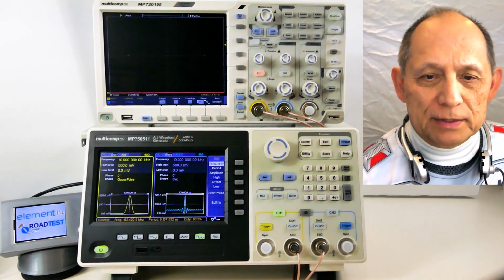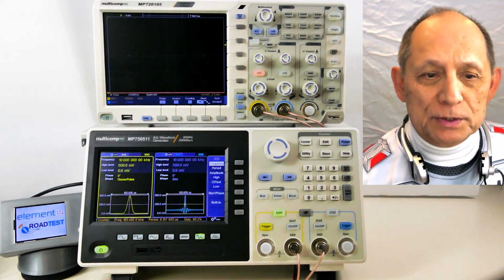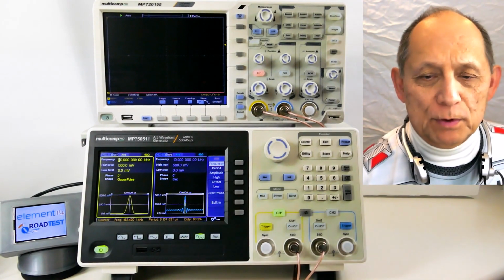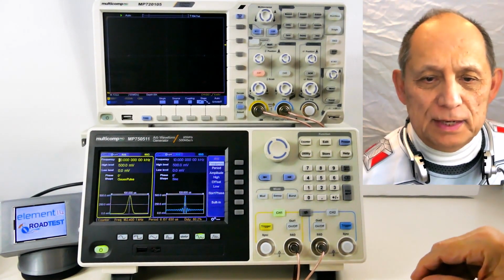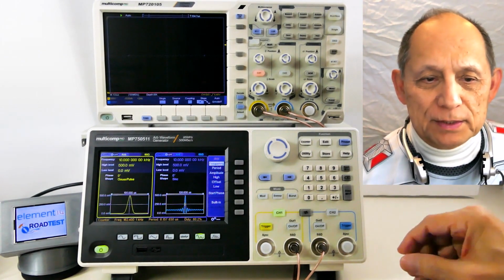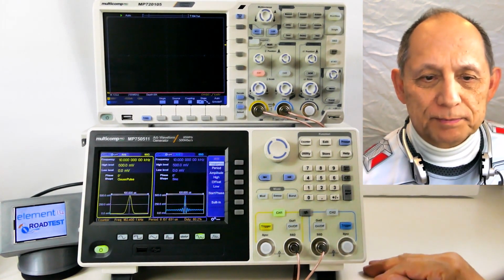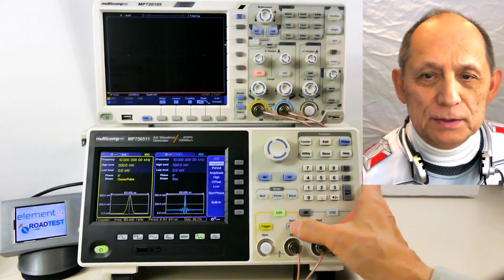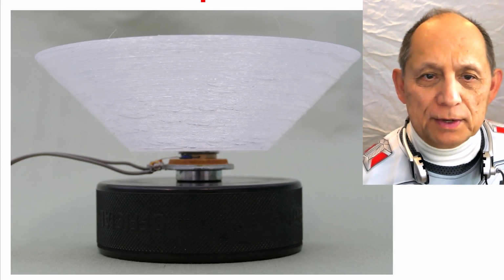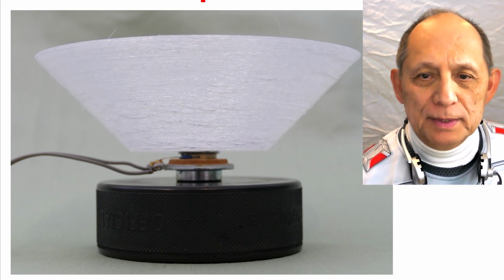Generally, waveform generators are very useful in being able to supply precisely specified waveforms to test the response and processing of any circuit. This saves a lot of setup time and eliminates uncertainty in test processes. For a specific case, I recently used a waveform generator to characterize the performance of a speaker. I programmed it to sweep a sine wave through the full audio spectrum and fed this signal through an audio amplifier to the speaker under test.